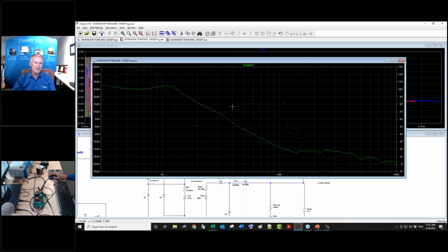It bumps the phase up sharper than it would, and it just gets all noisy out here because it's saturating the op amps. So this is a system where we drove it too hard. The LTspice system is exactly like the hardware. You have to shift the signal size with frequency, and we set that up for you automatically. So if you've got Ridley Works, you just export the model, and it sets up the source size.